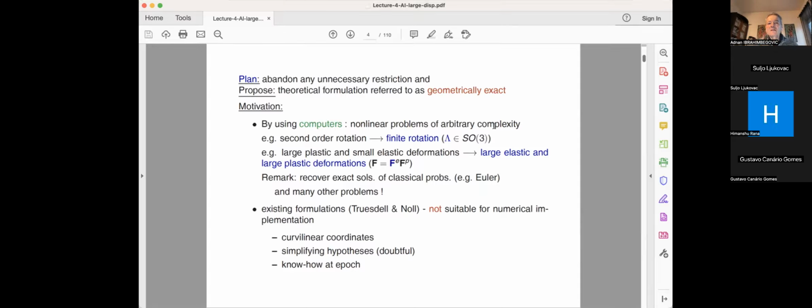But basically, this is really in 3D. In large deformation, we actually had to deal with 3D, because in 1D, large deformation is not so exciting. It simply reduces to a stretch. But the real difficulty starts when you have so-called large rotation. We do have a special class of problems where rotations are large, but strains might be small. This is typical of structures like plates, shells, and so on.